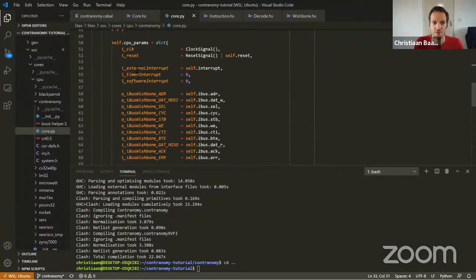And then here, we specify how the generated Verilog should be integrated into the entire system on chip. The way this works is that this dictionary, because it's prefixed with I underscore, it will know that this is an input, so it will hook it up as an input. And if it's an O, it will hook it up as an output. So this is all Python dictionary magic under the hood.